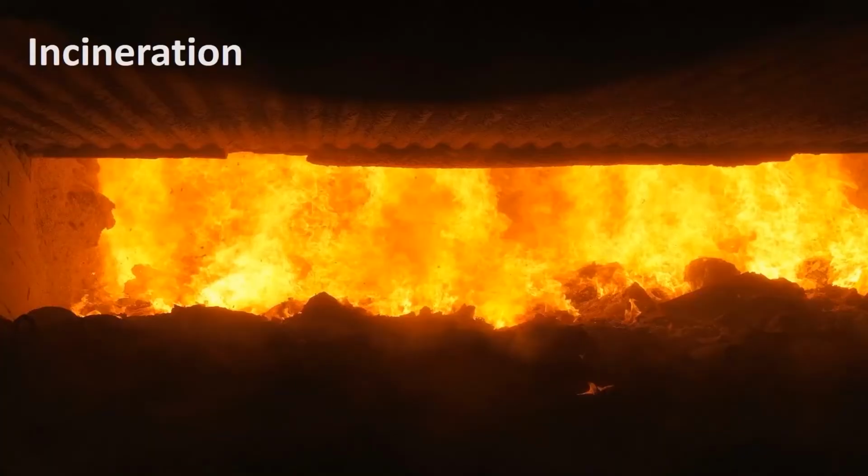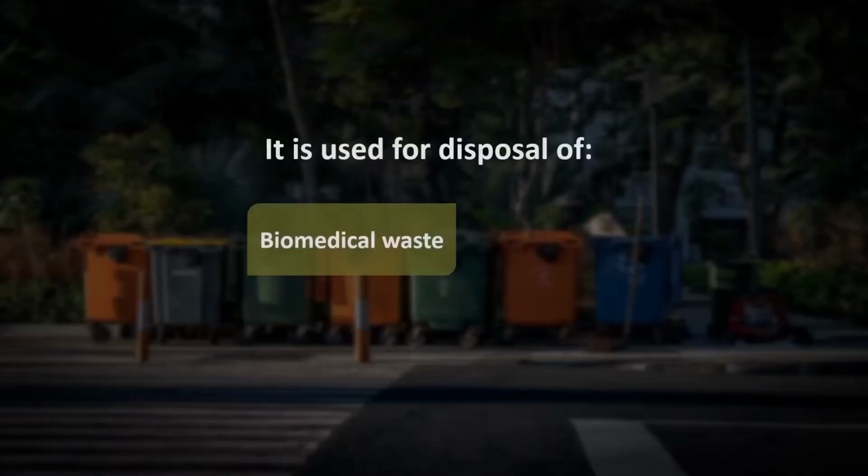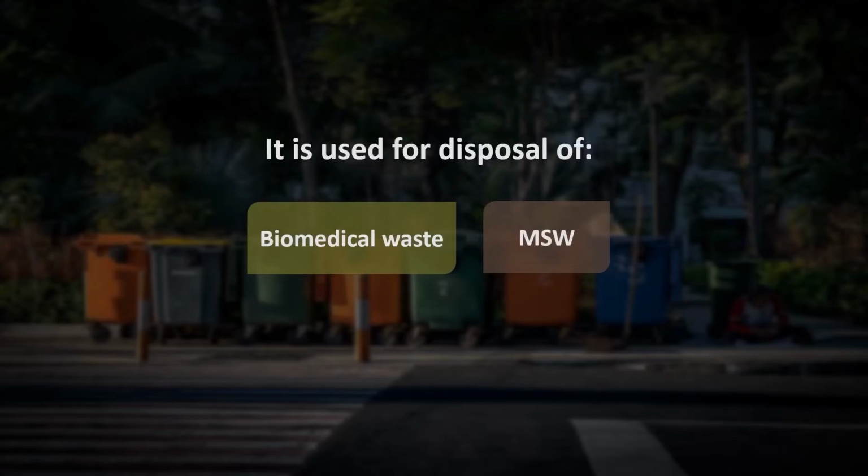Then incineration. For most of the hospital waste, and for certain instances, we follow the incineration method where the waste is burnt at a very high temperature, and almost 90% of the waste is eliminated by this method. However, we generally do not prefer it because it adds another problem where one problem is solved. It leads to air pollution, a cocktail of harmful gases, dioxins and furans, emitted when different types of waste are burned together.